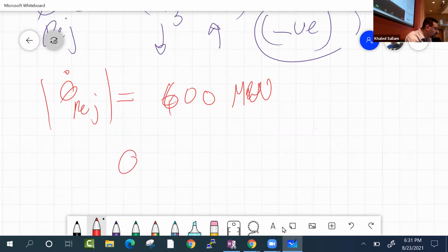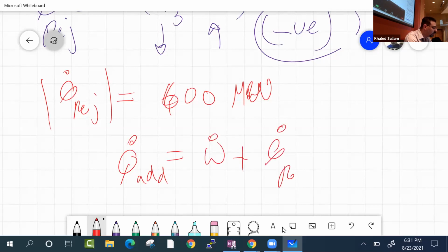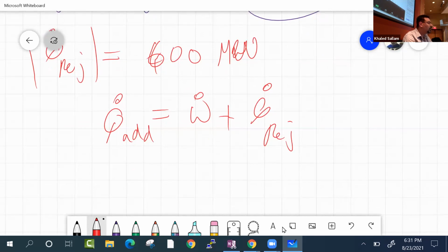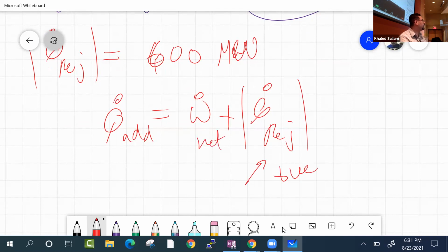And so when you do the first law and you say that Q dot added, because of the quiz that we're going to do today, Q dot added is work W plus Q dot rejected, this is actually expecting this guy to be positive, right? Don't come to this equation and say, but my Q should be negative according to the first law.